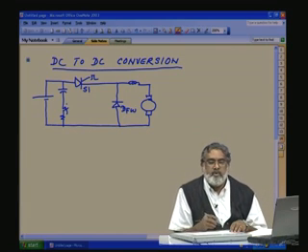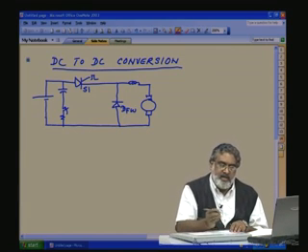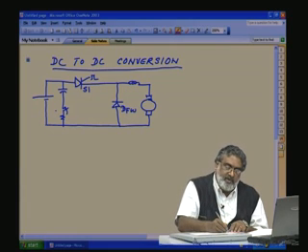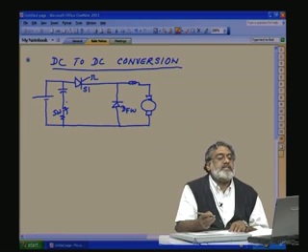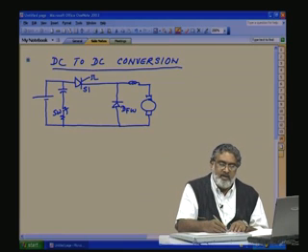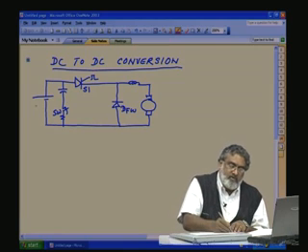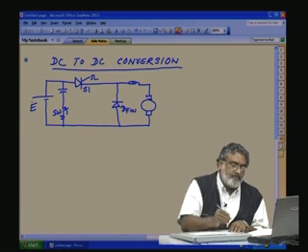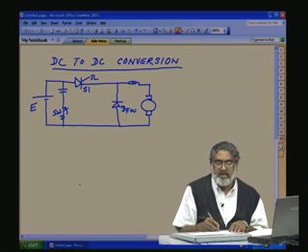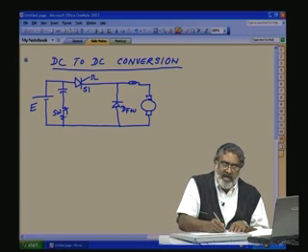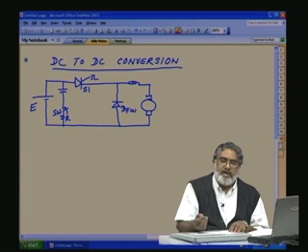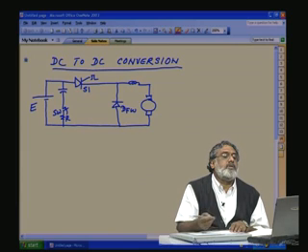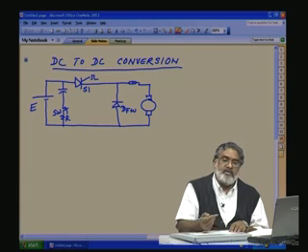So, during turn on of the chopper circuit or DC to DC converter, first thing is you have to turn on this switch SW, such that the capacitor will be charged to input voltage E. Let us say this is E. Knowing the R and C, we know the approximate time constant. So, through a monoshot, we can turn on this switch and after that we can switch it off.